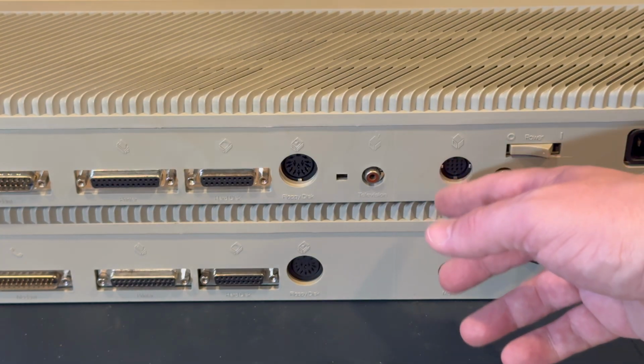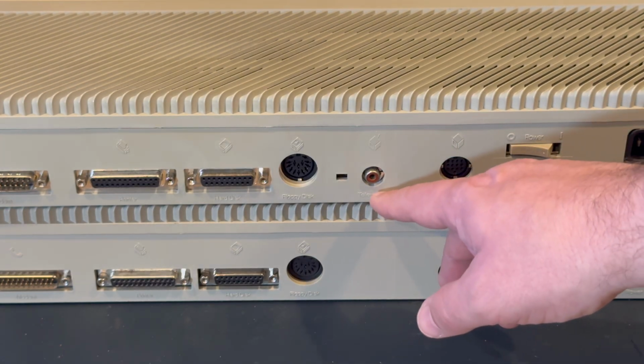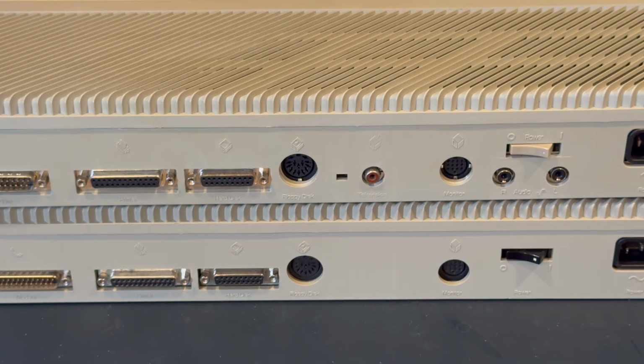That the RGB signal, the audio, that mono signal output, all input output, all come out of. Right. However, a number of Atari STs also include an RF modulator output. It says television here. This is an RF modulator output. Those are typically denoted by an M in the title of the machine: 520 STM, 520 STFM. The M refers to modulator.